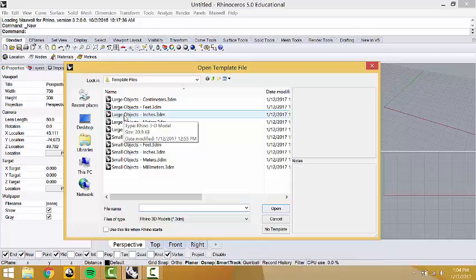As a caveat, which we will get to soon, when you are 3D printing, everything comes out as a millimeter. No exceptions. Because that's all the 3D printers think about are millimeters. And they care not for centimeters, nor inches, nor feet, nor any of these things. So units are important. You can modify it later, but it comes with some confusing scaling mechanisms. So it's best to always think about the scale the second you open the document.